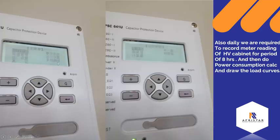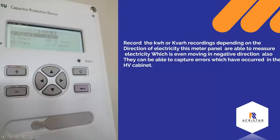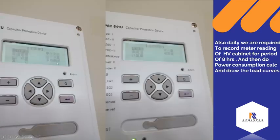So to collect the active and reactive power, this is the procedure we use to collect those data. We usually press Q, then enter. We have this menu. Then you press enter, then you press the fourth item. That is where you will find the active and reactive power data.